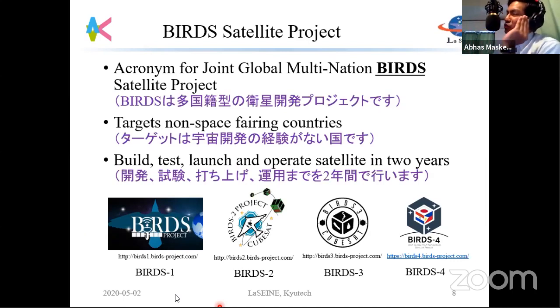But an MCU is just a single thread, so you need a higher frequency to calculate faster. I think that's the case. And also, I think STM32s have floating point units, which is very good. If you have a higher frequency with MCUs, you can use FPUs as well.